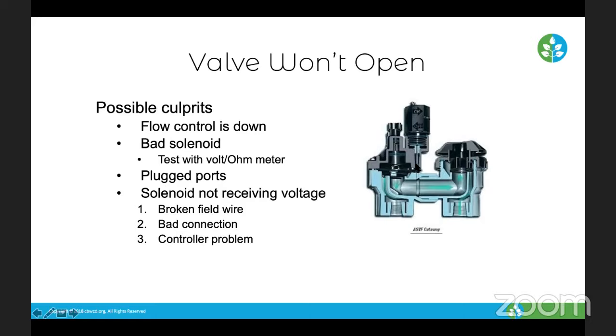Ports can be plugged. The port for the solenoid, and also the port going past the diaphragm, can get clogged. This does happen, especially if you have a lot of hard water. If you're pulling from well water, I know San Diego County has more issues with that. San Diego County typically uses valves that have stainless steel internal components to help with that.